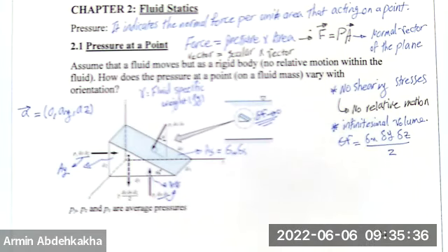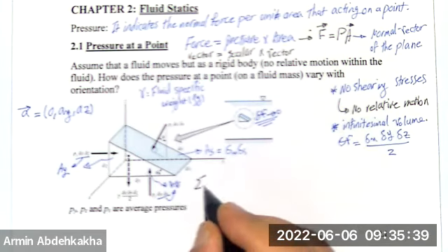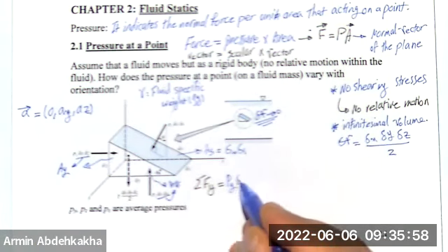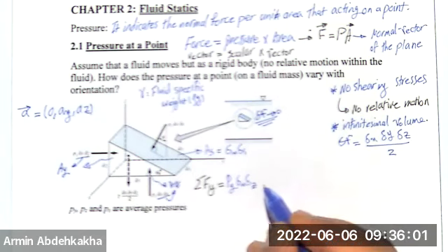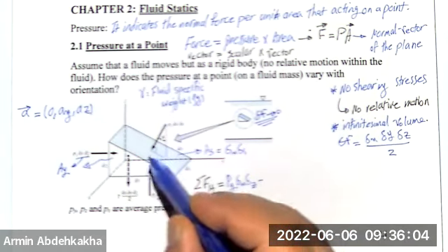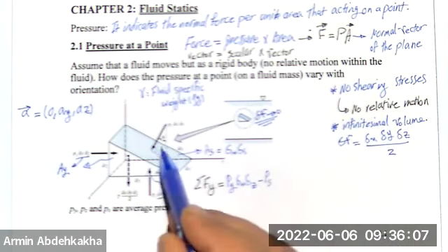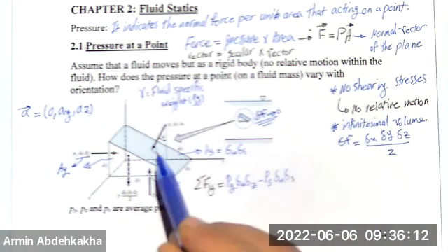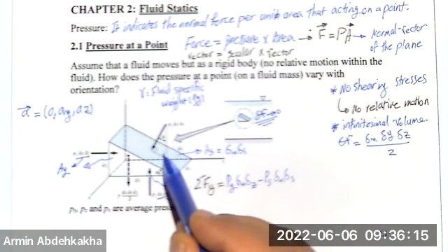Okay, so what do we want to do? Outside we had sigma Fy. In y direction, we want to write the summation of the forces. At first, we have Py, which is here, one force in the positive y direction. So Py, pressure at this side, times delta x times delta z, minus first Ps times delta x delta s, but in the y direction.